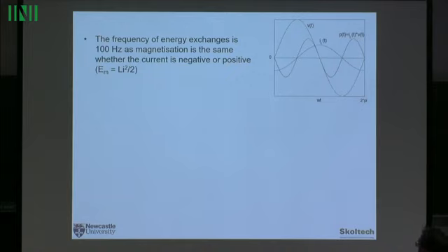is inductance. So here you have again voltage and current shifted by 90 degrees, and that red line is the product of the two. So you can see when the current is increasing, the energy flow is positive. When the current is decreasing, the energy flow is negative, and it repeats itself twice every cycle. Okay? Once again, current is increasing.